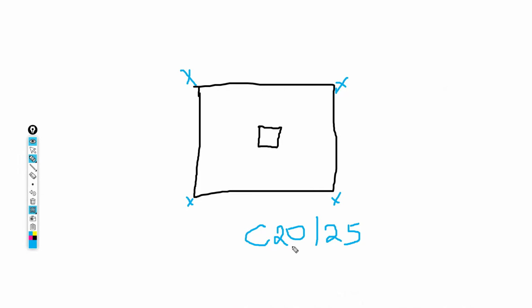So it is in the compressive strength test that you verify the grade of concrete to be used. The grade of concrete we are adopting is C20/25. C20 means that this is a cylinder strength.